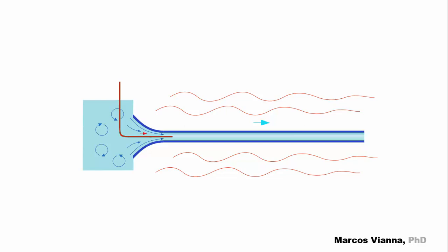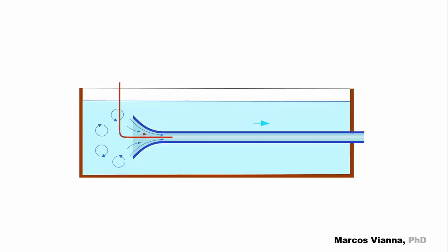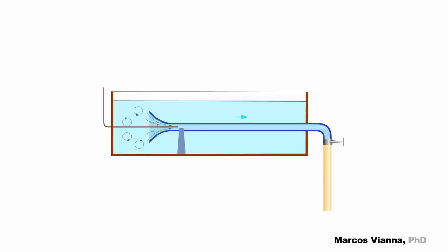But temperature differences could exist along the pipe. Viscosity value changes a lot with temperature. So, to prevent these differences, the entire device is submerged in water. There is a support to keep the device from falling. Okay, to maintain symmetric conditions, the dye injection will be installed like this. In the outlet, there is a flow controlling valve.